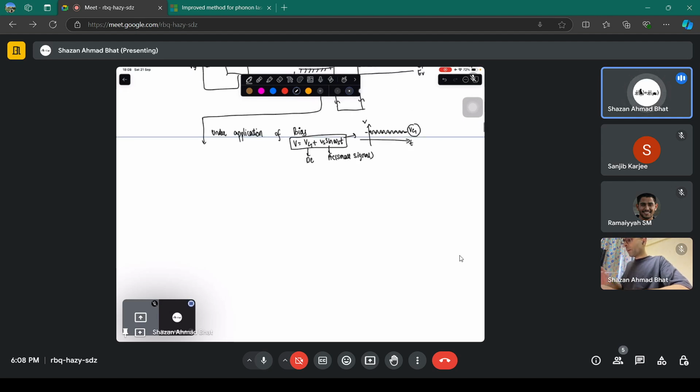So we are superimposing some small AC signal to study how the charges are responding at higher and lower frequencies. We are going to study that because at a particular single DC level, we will not be able to know how the charges will respond. In the end, what we have to give to the device are some alternating, fluctuating voltage levels. That is what the device should be able to handle, and that's why we test the device for this small signal also, along with the gate voltage VG, which is the DC voltage.